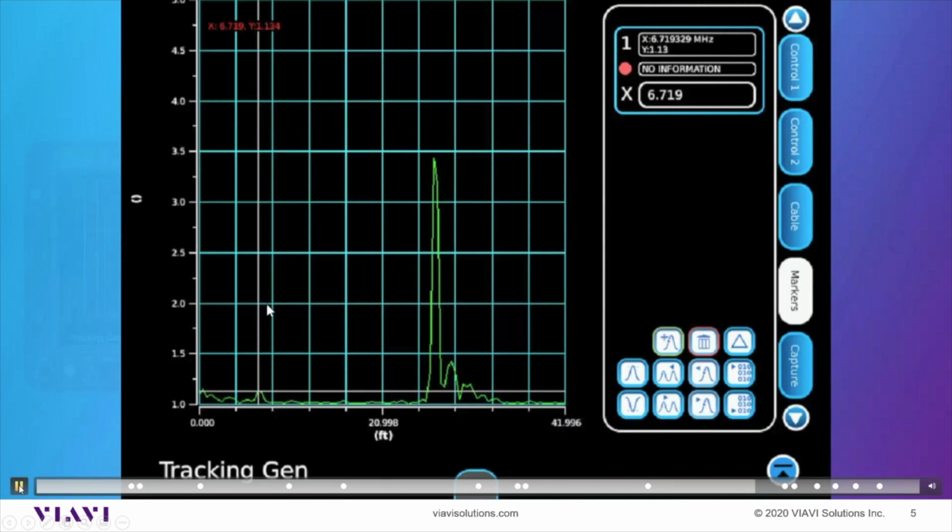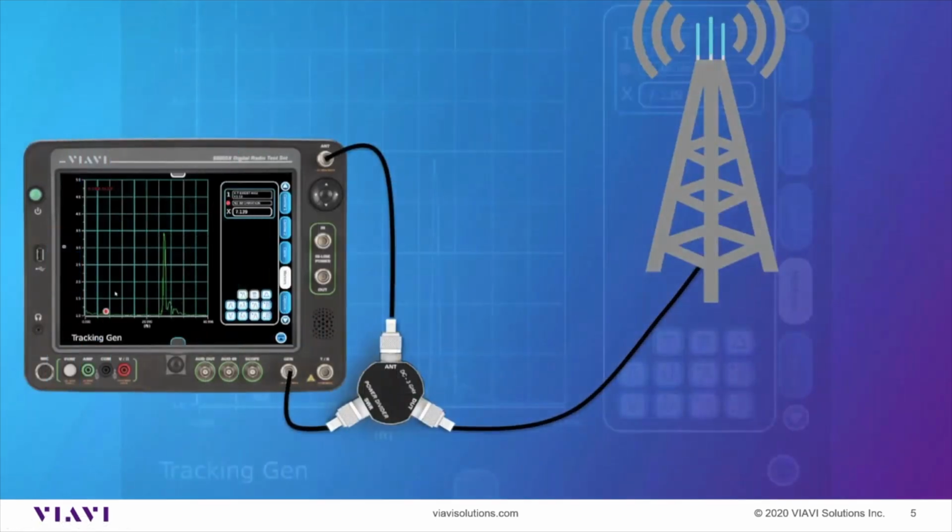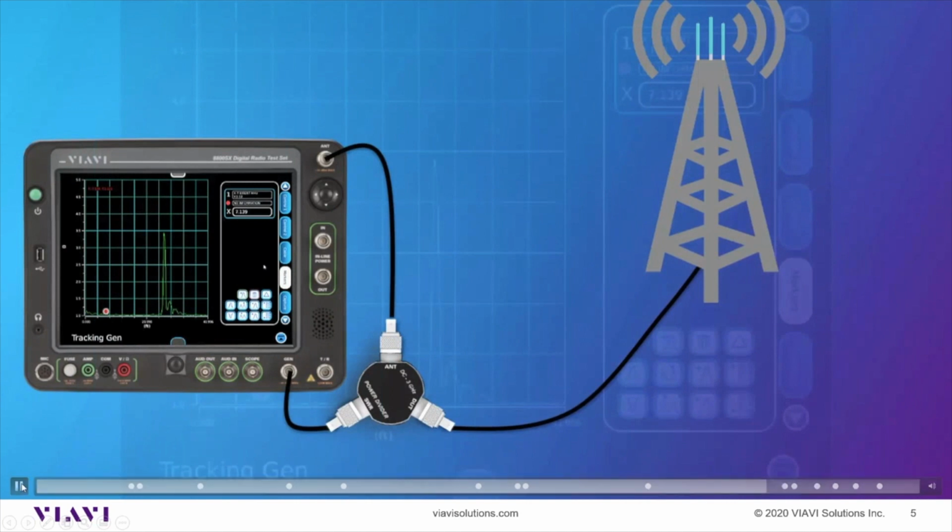I'm moving the marker on top of it here is what I've done. And it's telling us that there is something out there at about 7 feet. And in the next sequence you're going to see here, I'm actually going to go out here and remove that coupler, and you're going to see this signal go up through the roof, because all of that signal is getting reflected back into our receiver at that point.